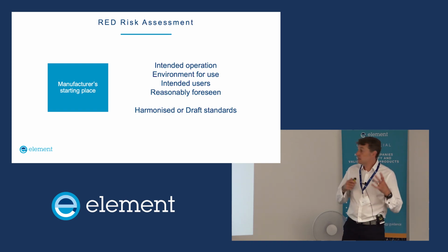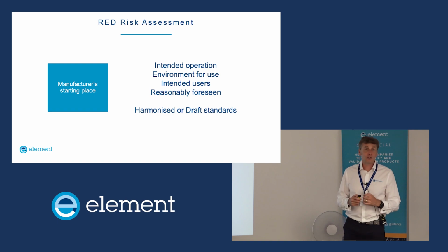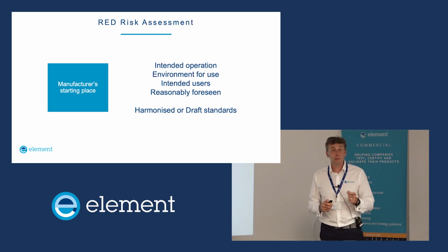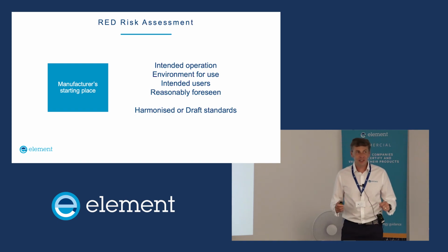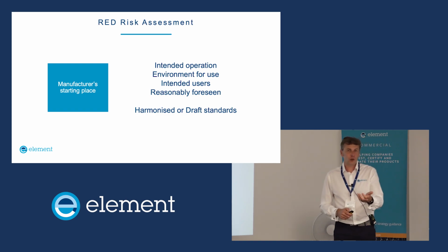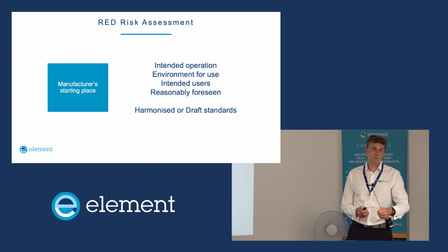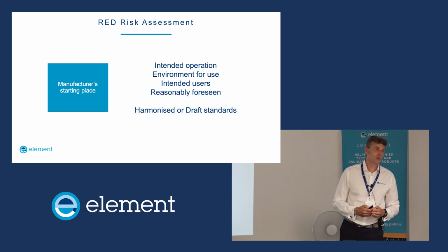manufacturer's starting place, think of things like who's going to use it, where it's going to be used. The RED says products have to be compliant for the reasonably foreseen use. So there's no putting in the user manual, you've got a phone, don't ever power it from a car USB port, please, because we didn't do vehicle transients.